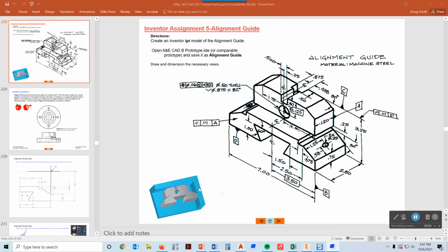So I'm going to actually model it that way. My origin will be right in here, and I'm going to draw down from the origin and start this corner and start my part. The way I'm going to draw this is because it's a symmetrical part for the most part, where this CL stands for center line running down through the middle of this thing. I'm going to use the dimensions from the center line over in this direction here, like this 1.5, the 2.5, and the 3.5, and then the 0.75 and some of these angles that I have, the 30 degrees.